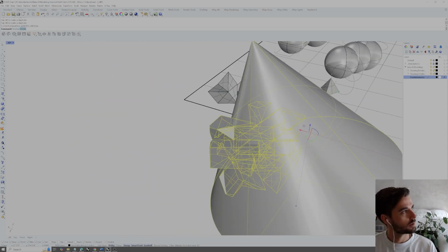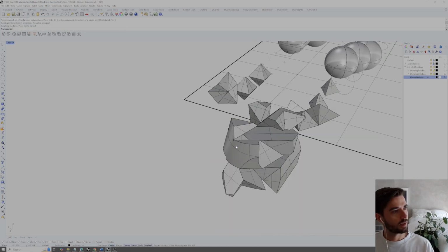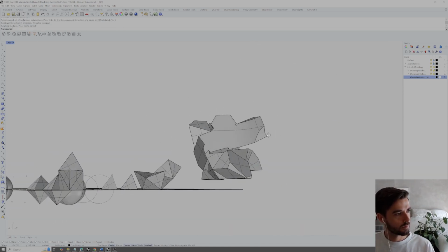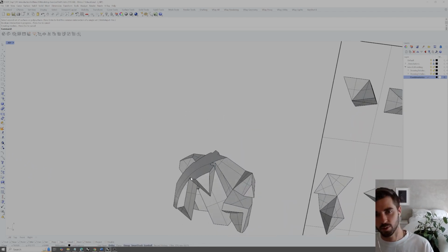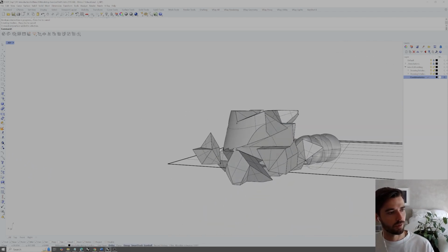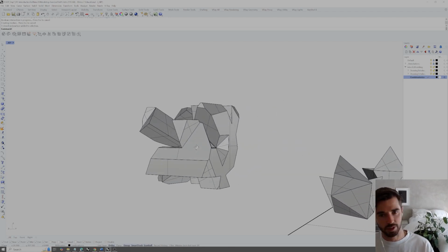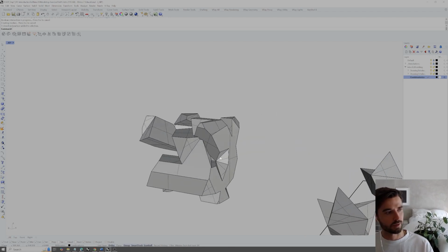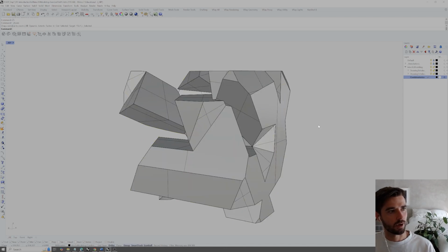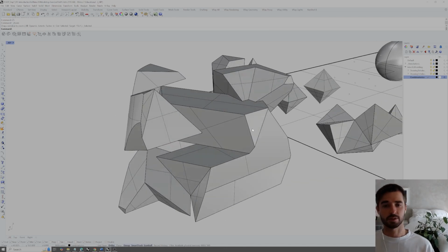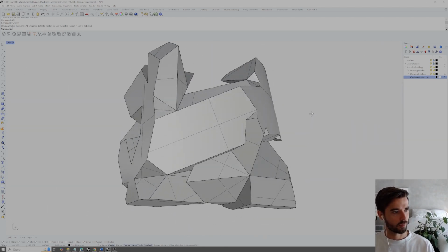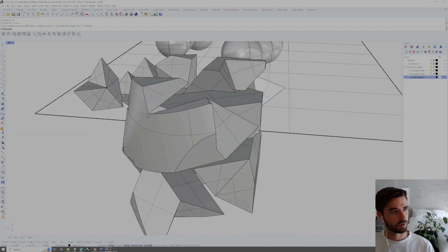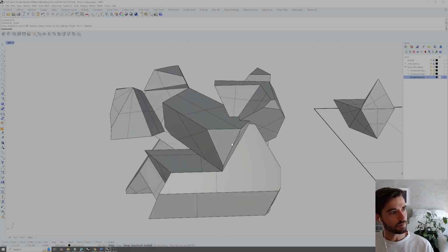Okay, let's try this. Boolean intersection, enter. Still a bit messy, but we're now getting this one sweeping surface moving through here with some of the patterns of the tetrahedral aggregation, and then some clippings from that bounding box on it as well. So we know that a cone is a singly curved geometry, and that's why I'm sticking with just using the cone or the bounding box, because we would still be able to unroll this surface geometry, or this polysurface geometry.